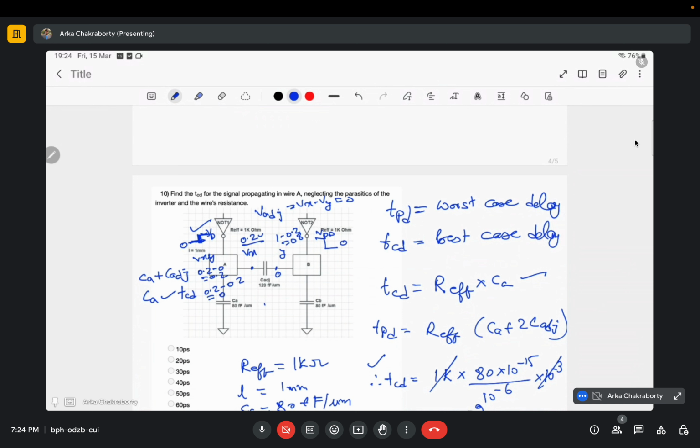I'm giving an example; these are not hard and fast values. Here it would be 0.2 minus 0.8, so around 0.6. The values that I have chosen are not correct, but the concept is that this Vx and Vy would be in opposite polarity. If I consider it 0.2, I might consider it as minus 0.2, not negative in the sense, but this voltage is in the reverse direction. It was charging, so this Vx was positive; it is discharging, so it would be something negative. It would be opposing this aggressor circuit.